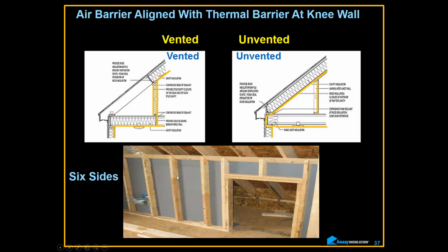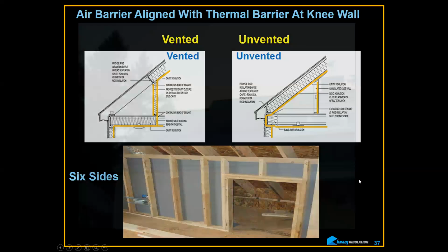Okay, here's the backing on one here. What is this lacking? What it's lacking is this block right up here, allowing the venting to go through here, but not allowing the air to wind wash the fibrous material. And the same thing here, you need a block directly underneath this, because you don't want wind washing coming from here back to here or into here. So you need blocking here. You can't see it here because you can't see the joist, but underneath this plate, you're going to need this block as well. 99% of the time overlooked.